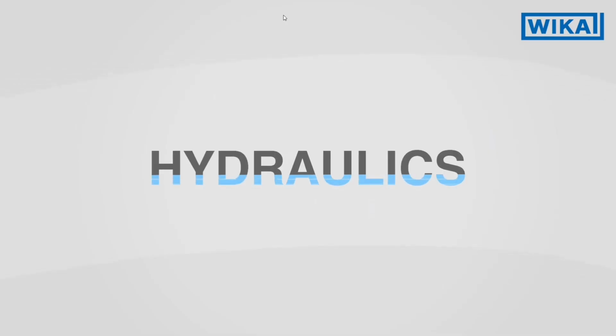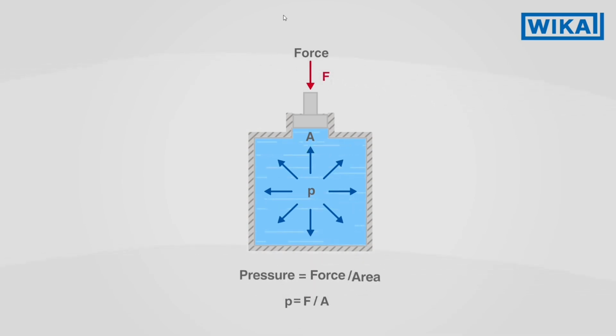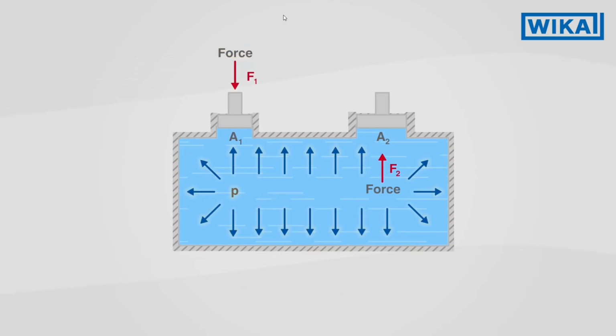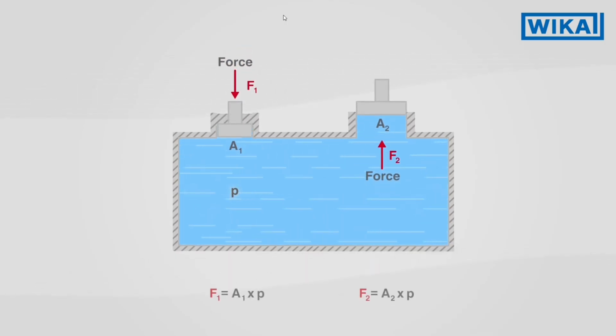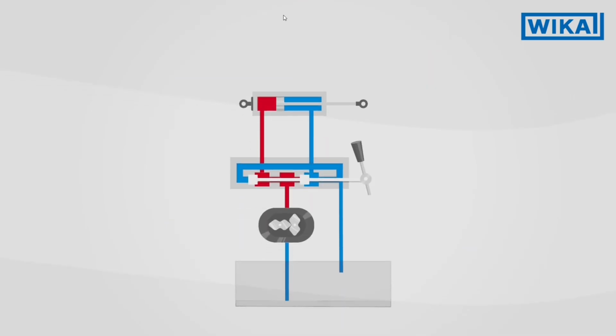Hydraulics is a technology involving the use of a liquid to transmit energy. This is where Pascal's law takes effect. If a force F is applied over an area A to a liquid in a closed container, the same pressure P is generated everywhere and in all directions of the liquid. This can be used to leverage the transmission of force. As the pressure is uniform at any point, the force applied once can be used on a larger effective area. Hydraulic systems work according to this principle.